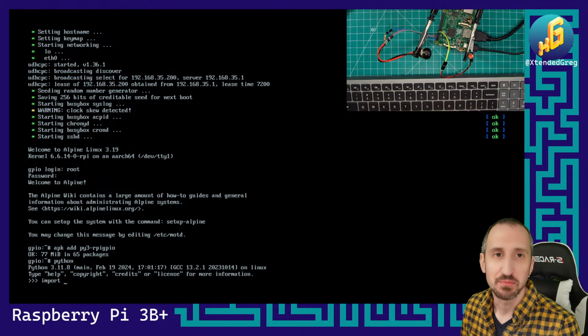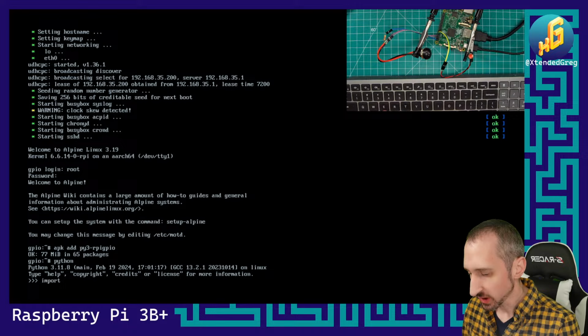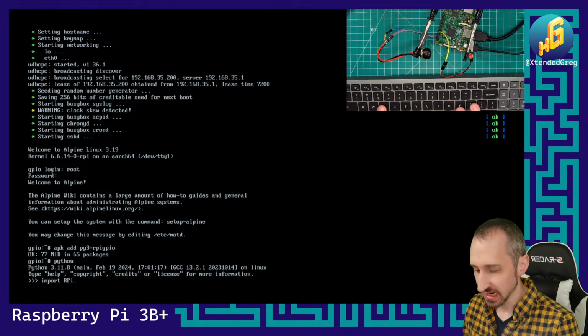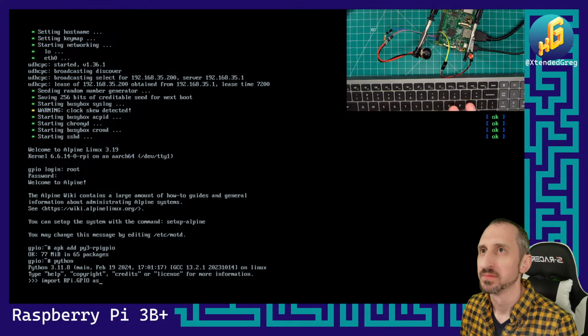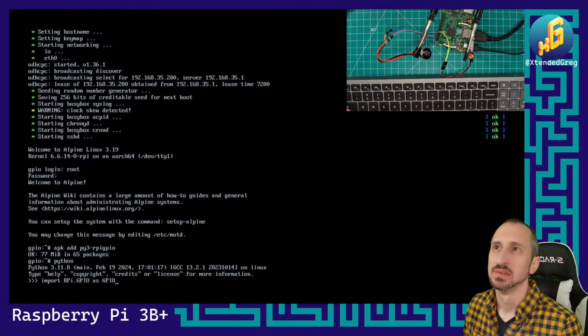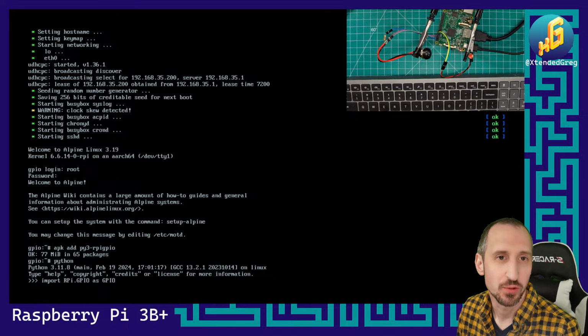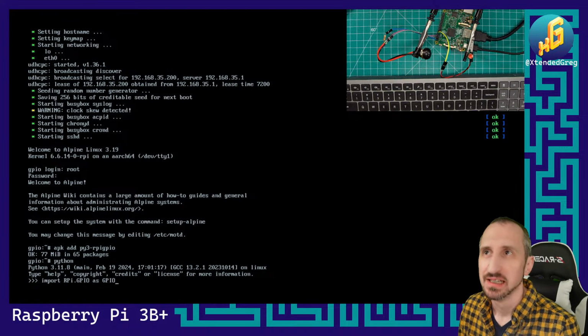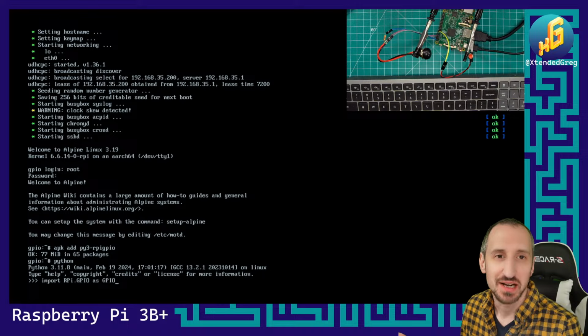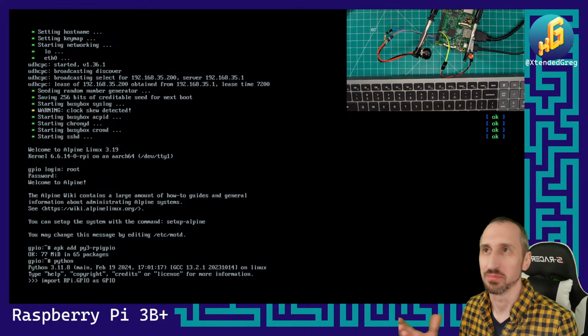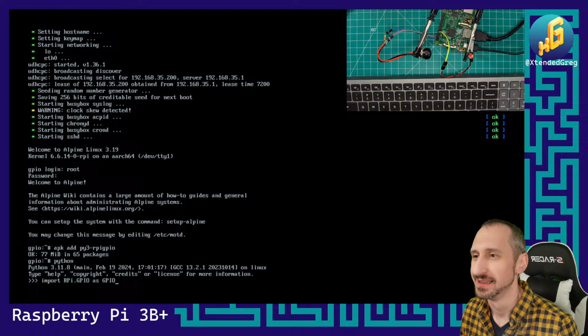And so we're going to use the import command. It's going to be import RPi.GPIO as GPIO. RPi is the library, GPIO is what we're calling out of that library, and "as GPIO" just means that we want a shorthand name for it. Calling it GPIO is going to be a lot easier than repeating the RPi part over and over again.